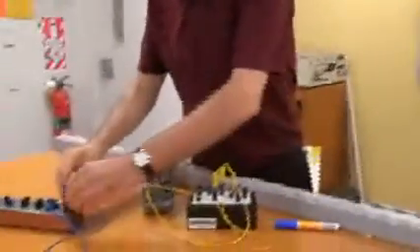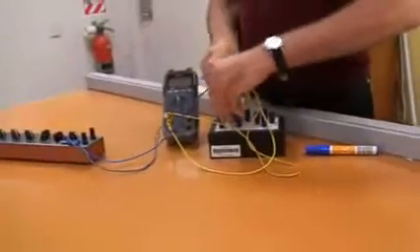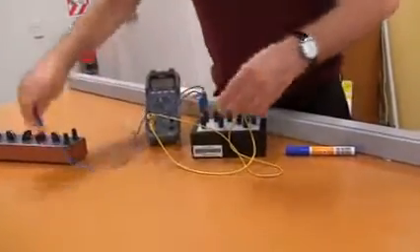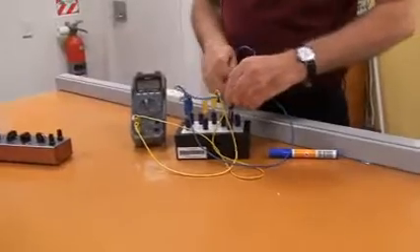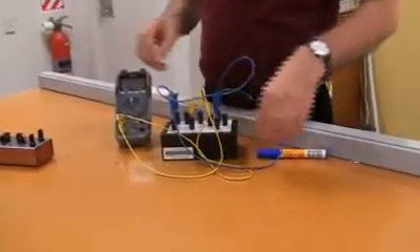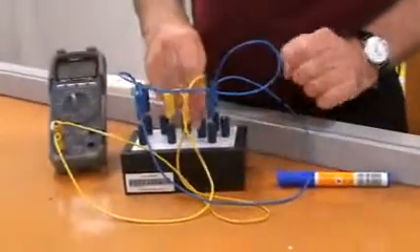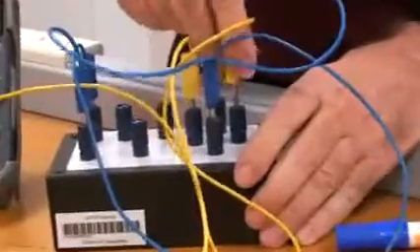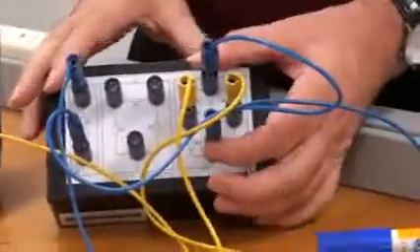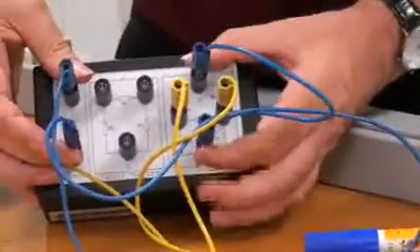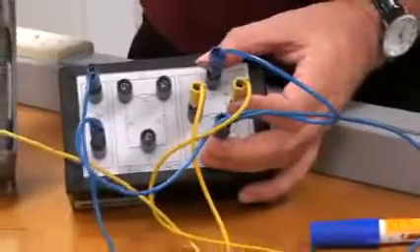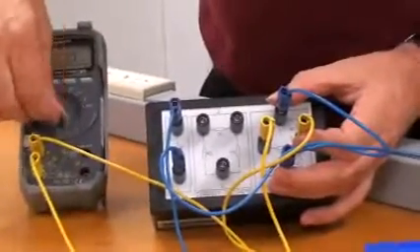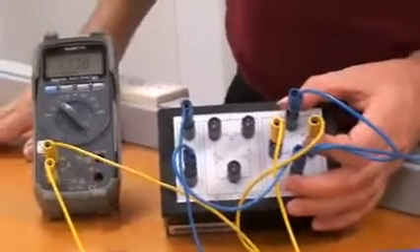Let's do that in the lab. So I'm going to take the supply from part A, and I'm going to connect it to the circuit for part C. Then I'm going to measure the voltage across F and G. So the blue wires are the supply, A feeds part C, and the yellow wires I'm measuring the voltage VFG. And I've got to go to the voltage range, and I'll get my answer.